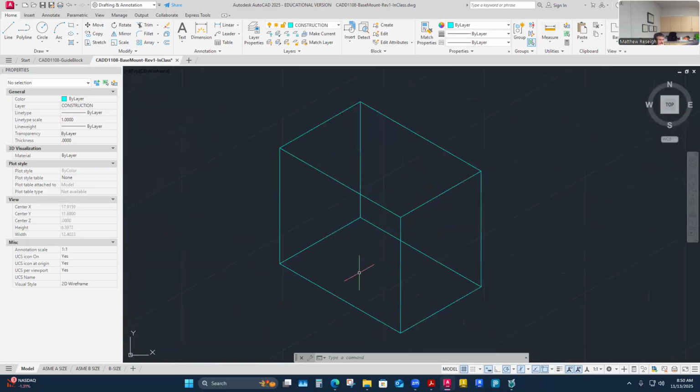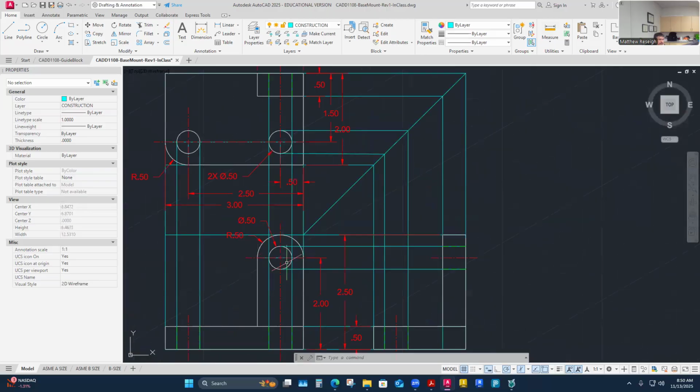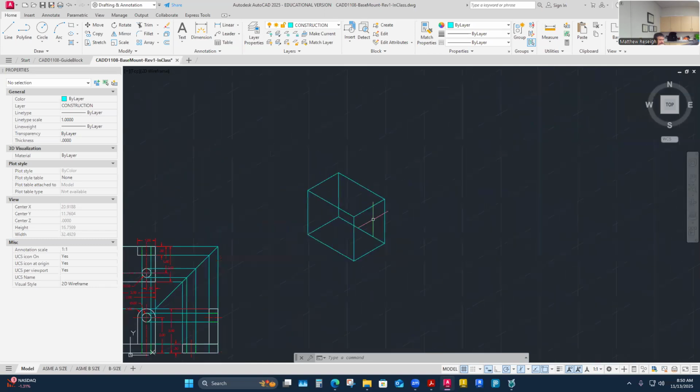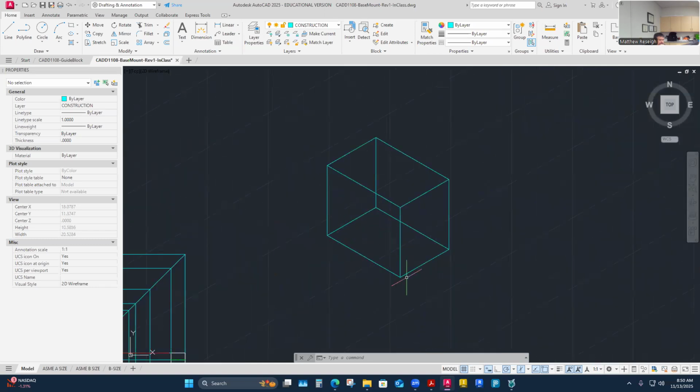So now I'm just going to draw. You could build this any of tons of different ways. I'll probably build the base plate that it sits on first, and then I'll build this little part. Then we'll add the holes, because even this radius will have to be, there's a command to do that. So let's start with the plate here. You're going to build stuff that becomes hidden behind. I don't use hidden lines, I trim out those lines that would normally be hidden. So I'm going to show it as a 3D solid view and not with hidden lines.